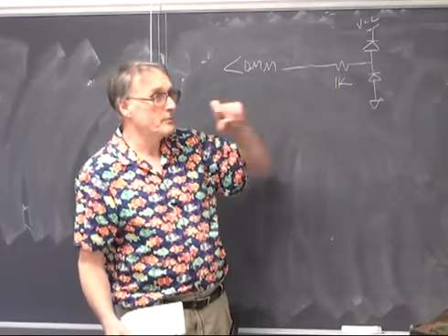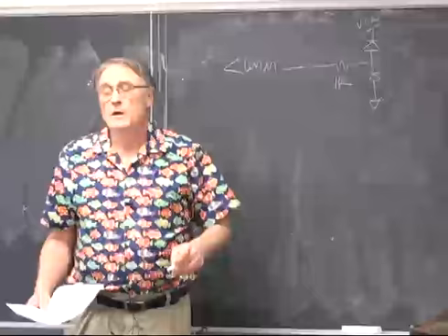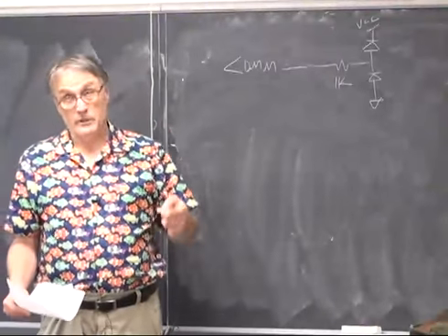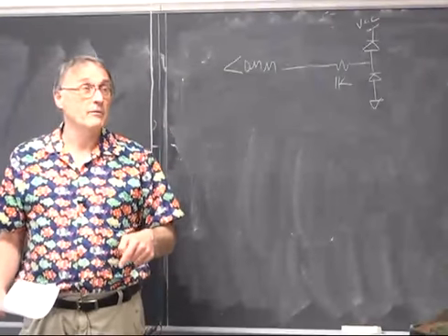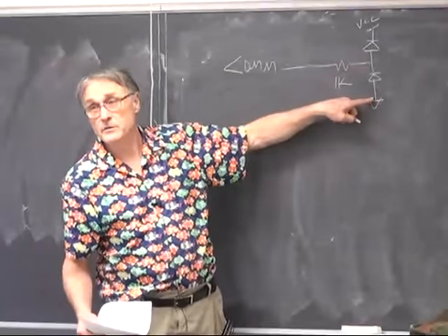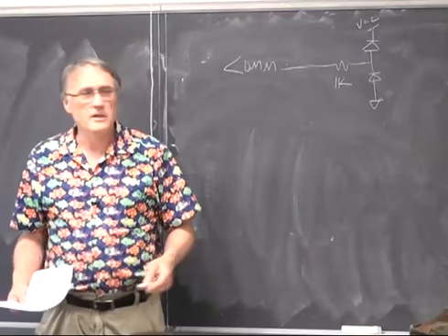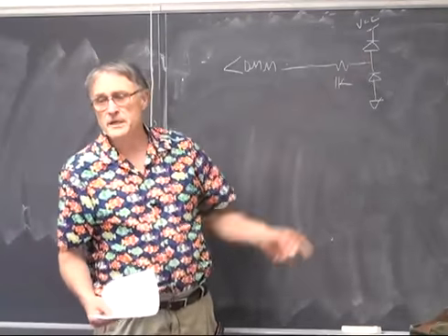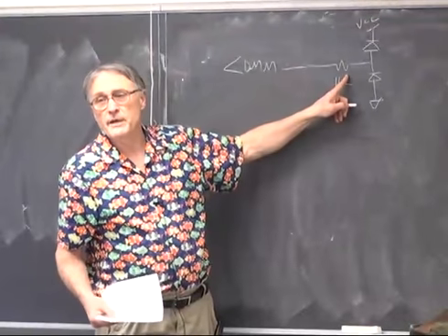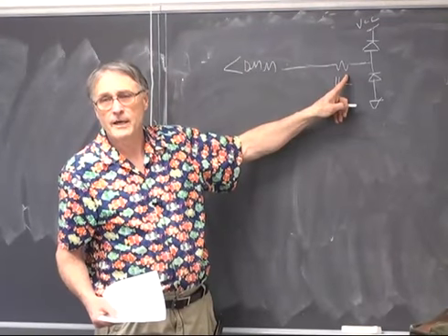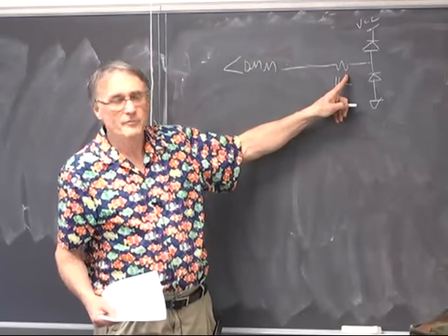This is pretty good protection of an input. The input to the internal circuitry of the microcontroller includes a pair of diodes, but they're fairly small and easy to burn out. You're going to use 1N914s here, which I don't think you can burn out with anything in the lab through 1K. But watch, somebody will prove me wrong.